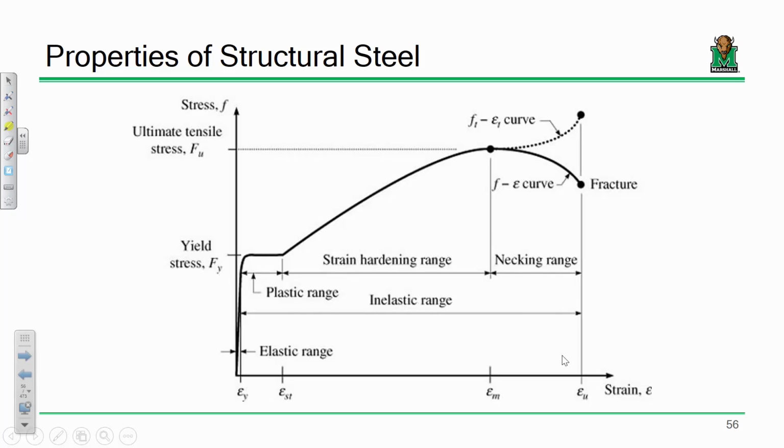This is one of the most fundamental curves that we generate in engineering, one of the most fundamental data sets, the stress strain relationship of structural steel. It is also really fundamental to our understanding of how we do things as structural engineers. Now, you might not have heard this before, but one of the things about structural steel is that it's very, very ductile. It has the ability to withstand a lot of inelastic deformation.